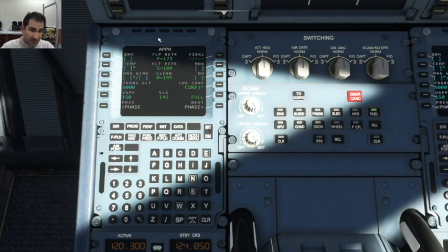And finally, for approach, you have more information. You see now the speeds are kind of consistent, flap retracted, slat retracted, clean. So this is information that is useful for you to check when you need to start retracting flaps, slats to reduce your speed at approach.